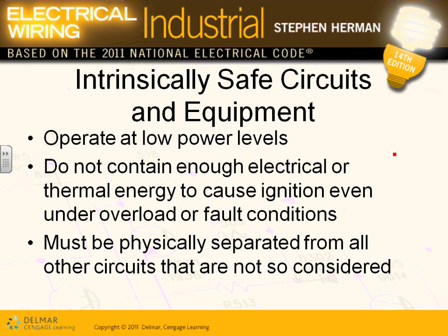There's something called intrinsically safe circuits, guys. For the most part, the wiring methods that you're going to use for these hazardous locations, class 1 and class 2, are threaded, rigid equipment. In class 1, class 2 locations, your wiring method is threaded, rigid conduit that you're going to put in these locations.